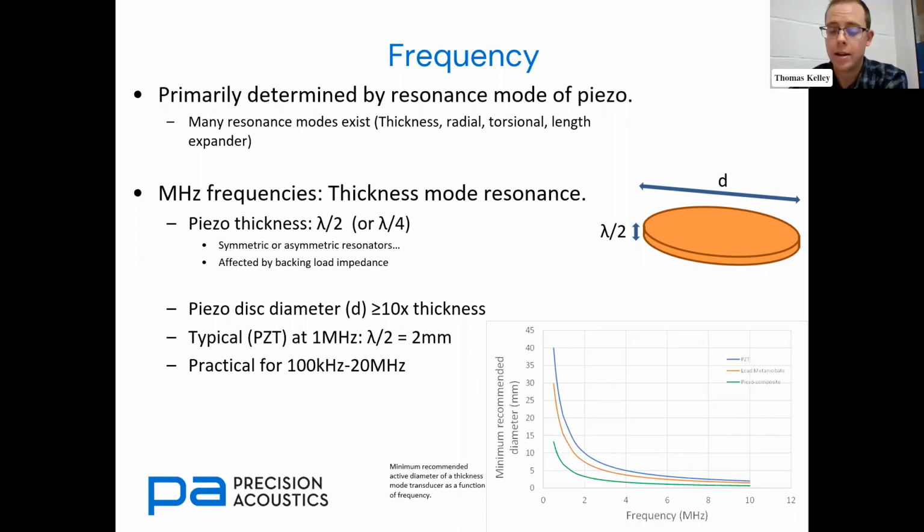Yeah, and you can look at the different films. You can look at thicker films and do the same comparison with diameter. The thicker the film gets, the less it is affected by the capacitance, or the less the frequency shifts as a function of area. Purely, it's the thicker film with the lower capacitance.